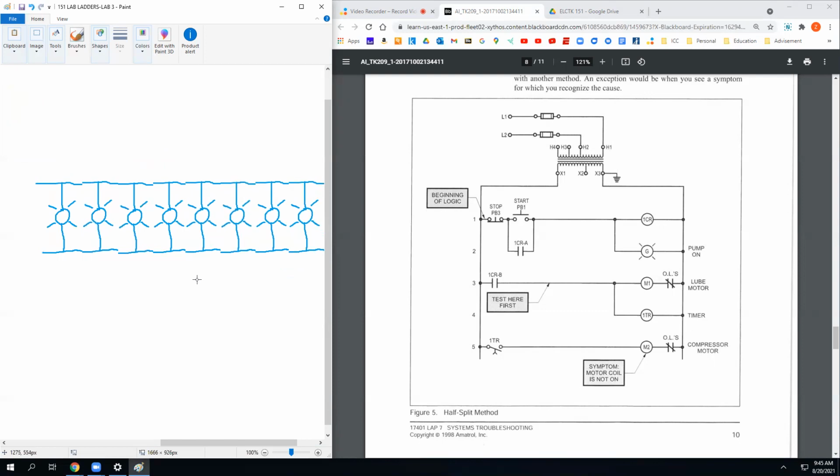It doesn't even have to be lights, it could be outlets. But somewhere in this system, let's say this is 277 volt. So L1, neutral, and this is 277 AC. Somewhere in here, on L1, you're going to have a fuse or a circuit breaker, are you not, to protect all this wire? So let's say this thing is on a 30 amp fuse.